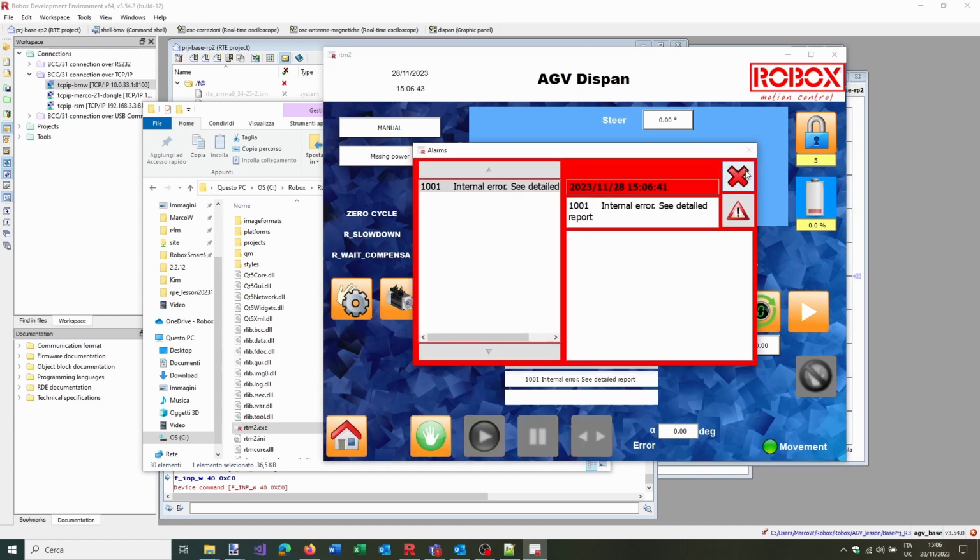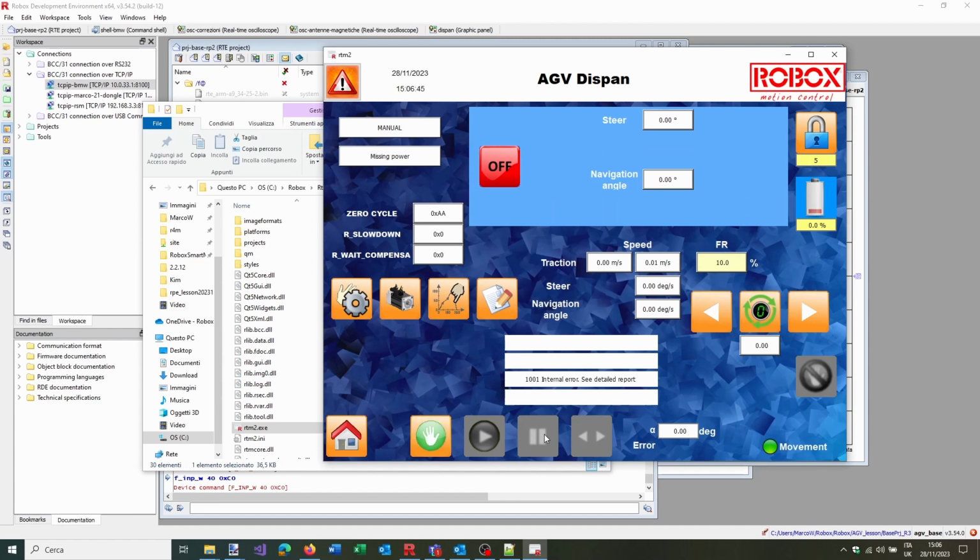After some time, even if I press forward, I have... sorry, something is giving a problem. I'm sorry. So after some time, if I'm not playing the axis, it will go back to 0, to stop, so there is a timeout. This button instead will change from manual steer to automatic steer. The automatic steer will use the gyroscope, if any, and so it will force the steer to stay at 0. While we use the manual steer, we may press right and left to move the steer, while pressing 0 will allow us to go back to the 0 steer.